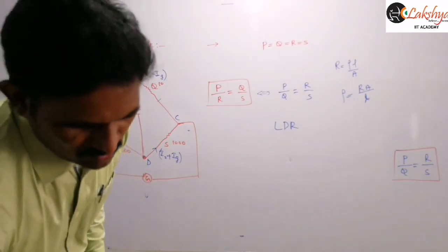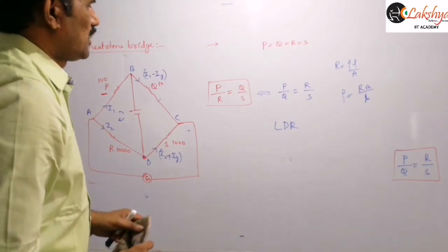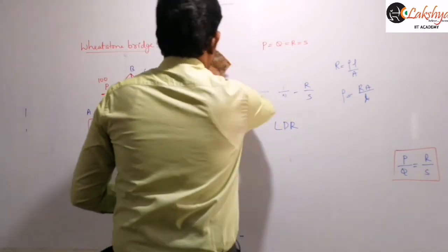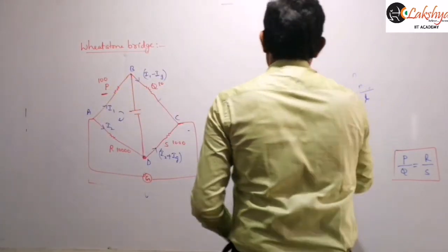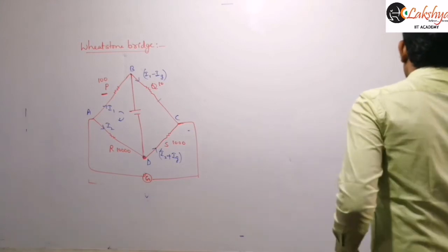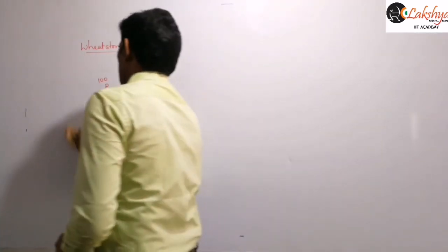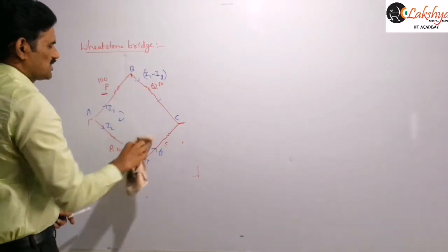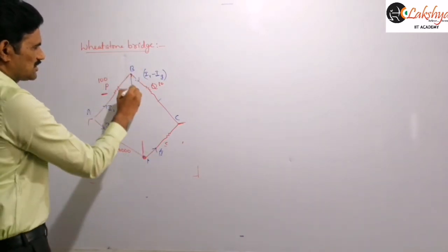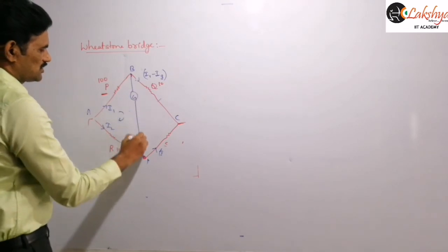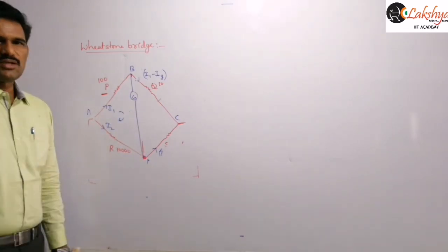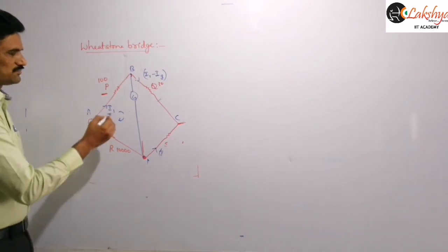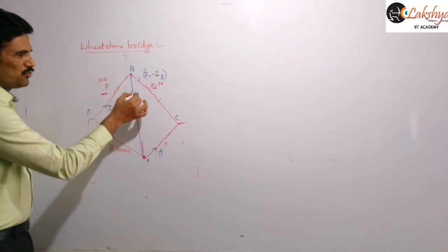And next, there are some different forms here. Now by using this Wheatstone bridge we can solve some circuits. That means we can find some effective resistance here. When you are finding this effective resistance, you simply need to remember when the bridge is balanced. Suppose in the usual standard I am taking that a galvanometer is present here, right? Now if this is a balanced Wheatstone bridge, then you can remove this resistance here.